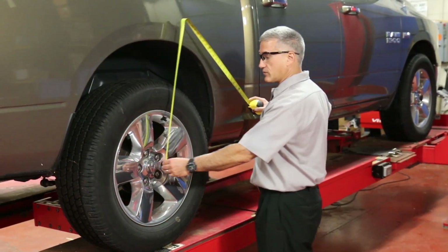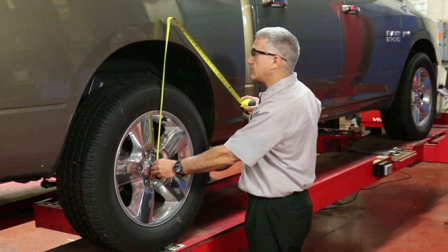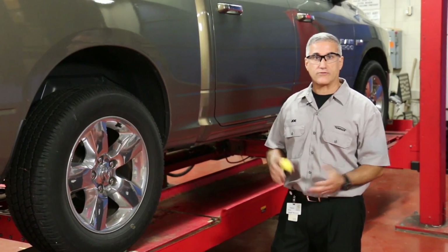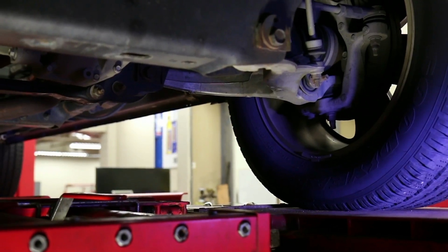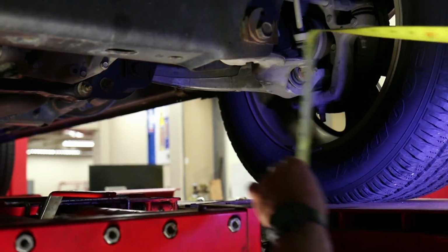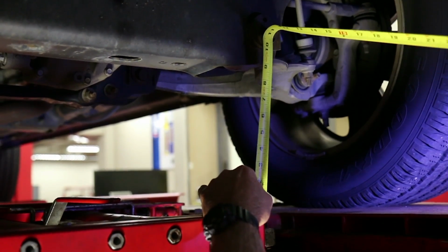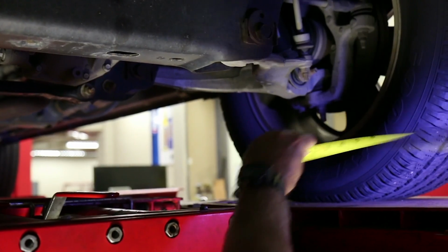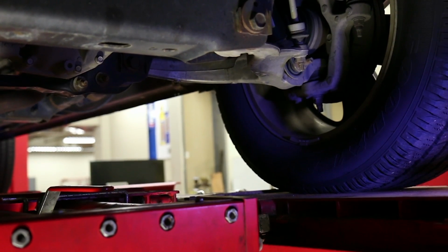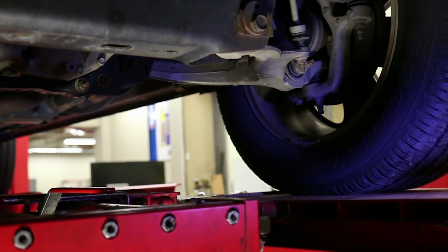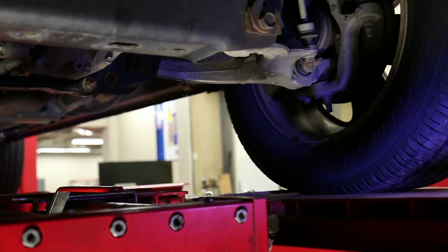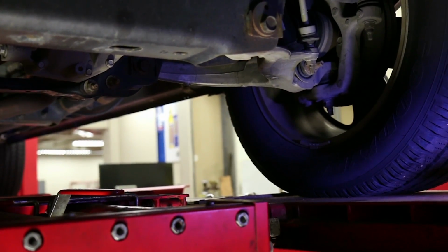Another good point, which is more accurate, is to measure from the center of the wheel right to the bottom of the fender lip opening, because that negates any issues with tire wear or different diameter tires. On many vehicles with full frames, the manufacturers will have you measure to the bottom of the ball joint and subtract that measurement from the suspension pivot point. As you can see in the simulation, when the springs start to sag, the measurement will get smaller, indicating that the springs need to be replaced. This type of measurement eliminates any difference due to variance in compression of the body to frame cushion.